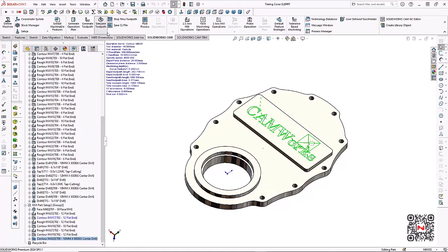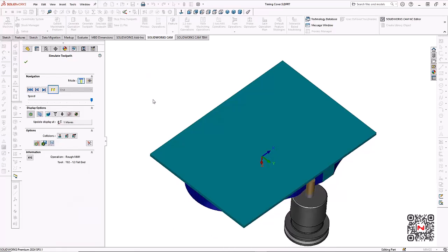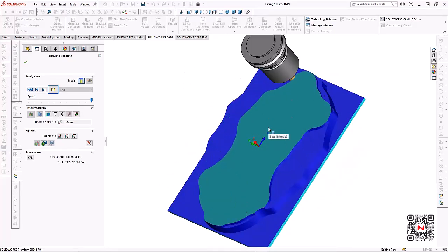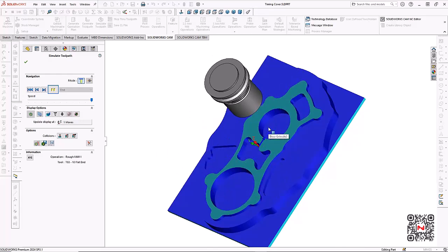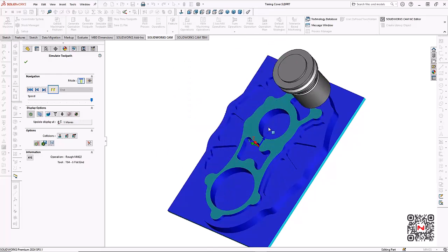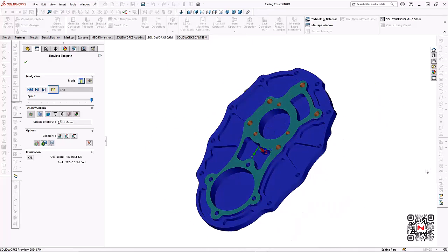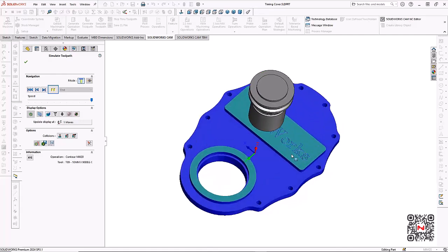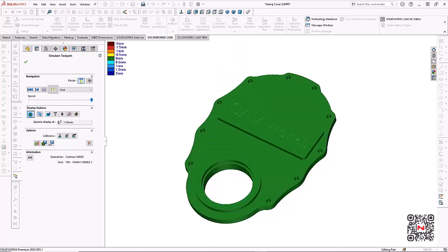And then we can go ahead and do the machining one more time here. Flip it over so we can see the first side being machined, the first setup. And each of these setups can have a different work offset number. I could also generate 2 different programs for these 2 setups if I want to do that. And you can see here where I've done the engraving now as well.